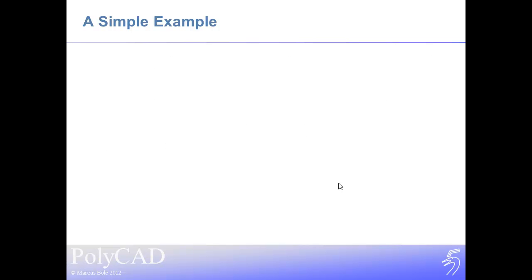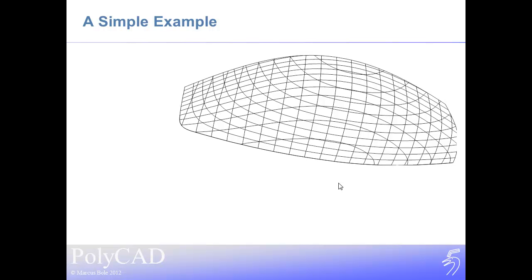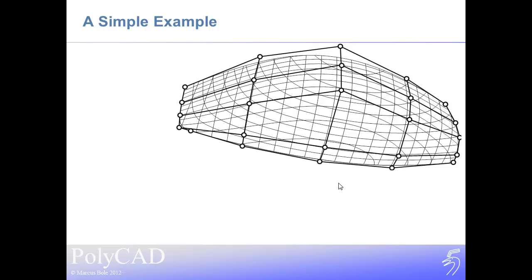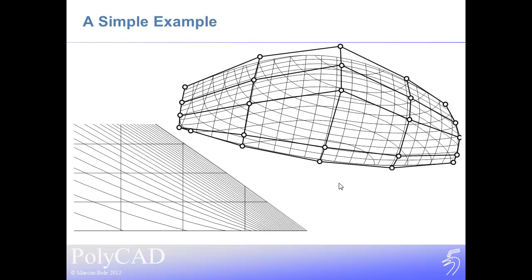Let's start with a simple example, the simplest of examples. This is a very simple, almost idealized yacht shape, developed in a NURBS, and we can see the NURBS control polygon here. This is the kind of first thing that we would do when creating a surface. But very specifically with this kind of arrangement of control points, we find that very near the forefoot of the hull, with this particular arrangement of control points here, where we attempt to make the corner of the surface hidden, we introduce a concave effect in the waterlines.